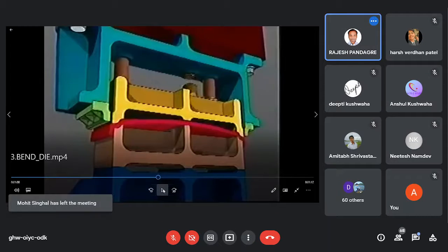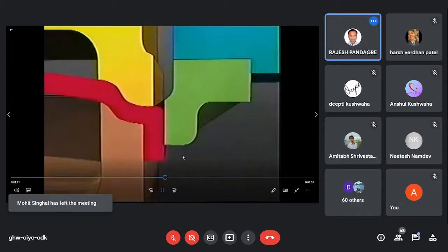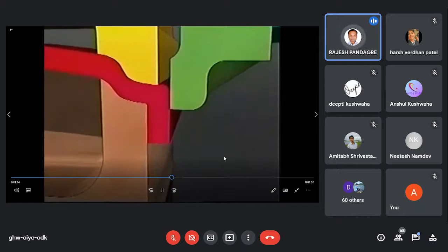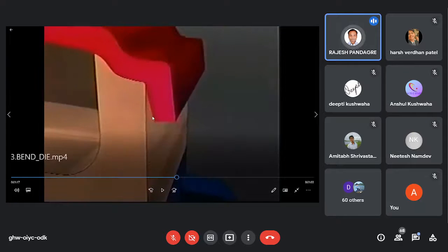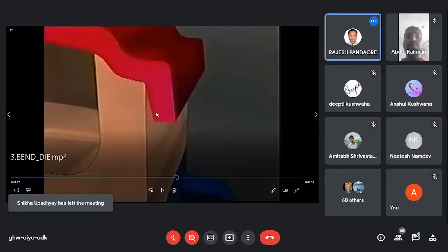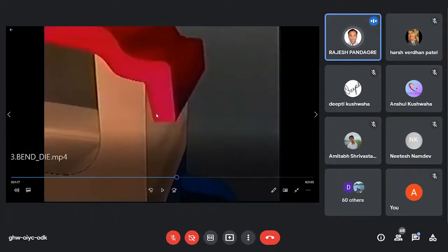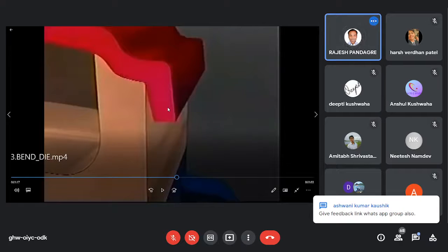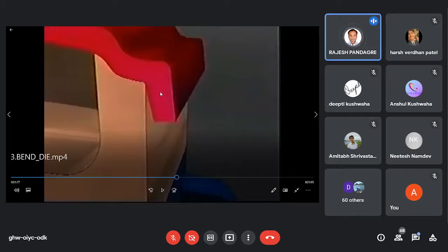That is the effect. Once again, when it goes back, the spring back came. This is called spring back. For that, we have to make some arrangement to get the desired shape. This is a very important thing. This problem is everywhere. With aluminum, or any sheet metal or steel material, everywhere we face this problem. So how do we reduce that spring back?